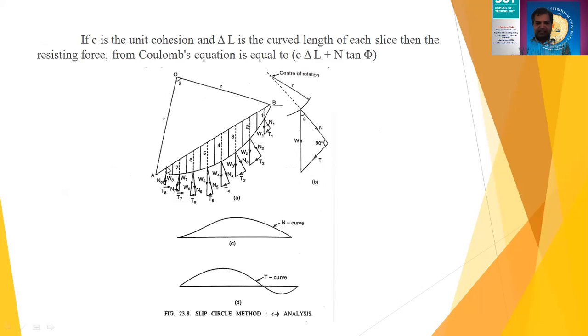You can see the slices we have drawn. I am assuming that the forces between all the slices are neglected. Of course, there will be a shear force acting on such columns, but I am assuming there will not be any force. And second, each slice has a unit width B and unit thickness, and it will act independently as a column of soil.